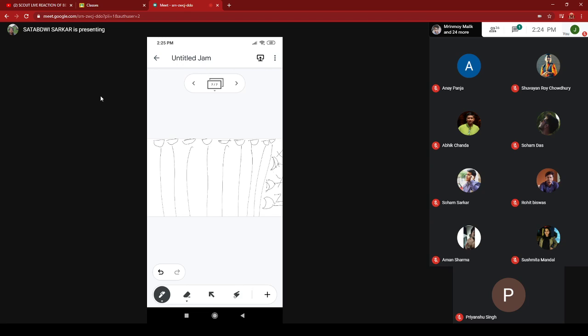Now we have to connect these OR gates depending on the functions, or depending on the terms, that is how many terms are present in which function. Suppose for X we have the function A bar B plus AC, that are coming from this first and second. Actually, we should not mark it with the cross symbol here.